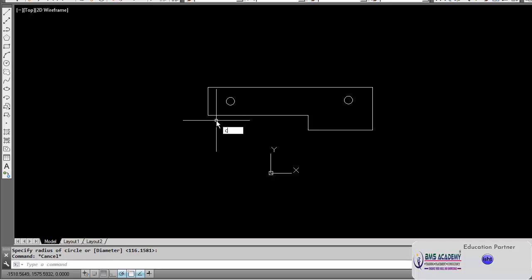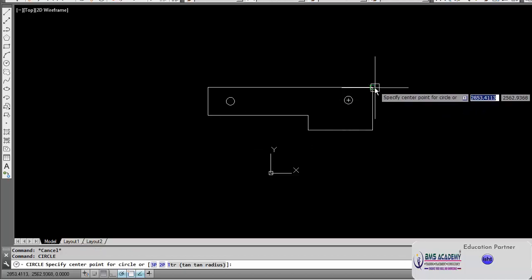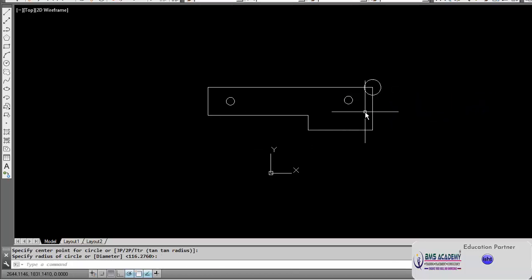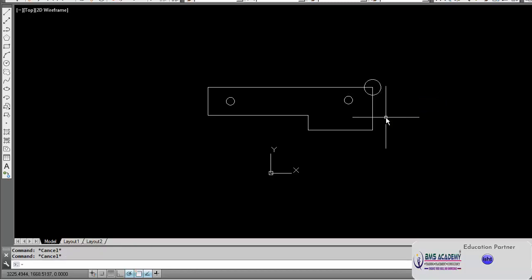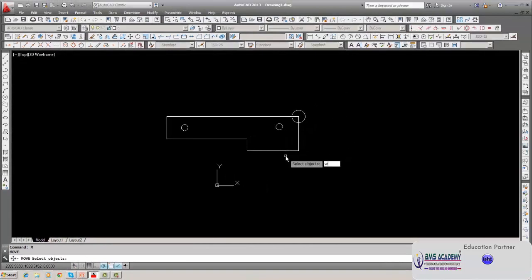What we do is, I will repeat the same thing once again. First we draw a circle here. Okay, this circle. You have to ensure that the circle is locked. It should not move. This is the benchmark for bringing the component back after dimensioning. So you select the component. Now I will tell you one more thing.